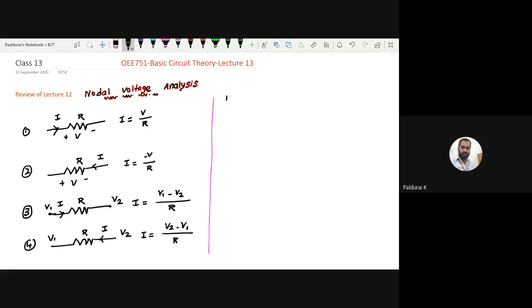Now coming to case number five, where I want to play with three voltage sources. Take this as V1, this as V2, and this as V3 with plus and minus, and this is R. What is the formula for I? As per my style, I equal to V by R. Here also it is starting voltage minus ending voltage, then minus, and for intermediate voltage sources put a bracket. That's the best practice. Then consider the starting polarity. Here the starting polarity is plus, so it becomes V3.